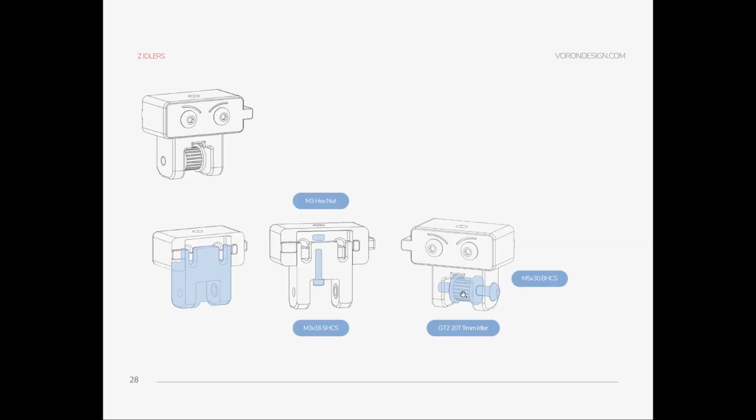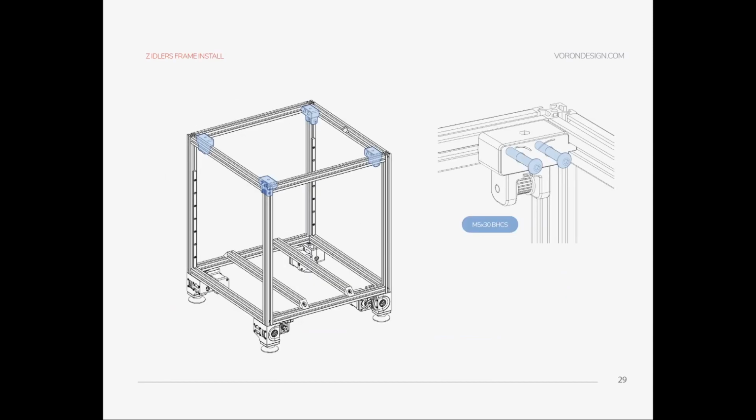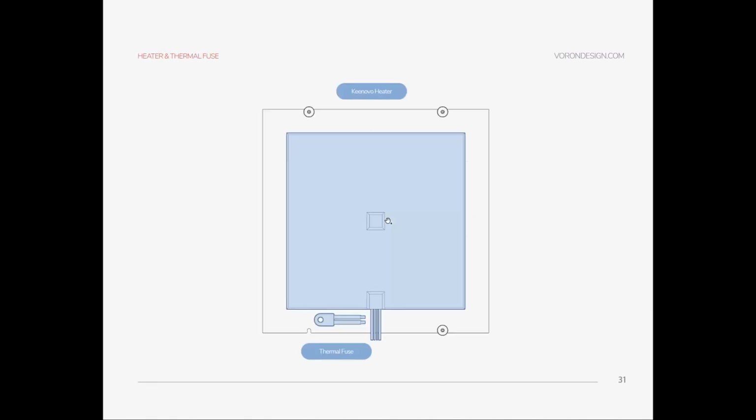And these pulleys need to rotate freely, as you would expect. So don't tighten these bolts. They should only hold this pulley. Just be sure that the head is flush with the plastic part, and that's okay. Don't tighten it. Later on, you are placing the Z idlers. Be careful about the orientation and the build plate.